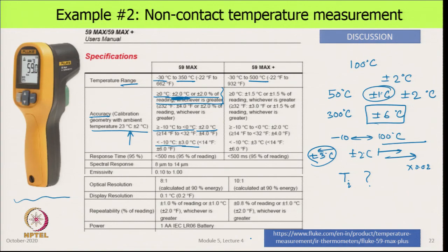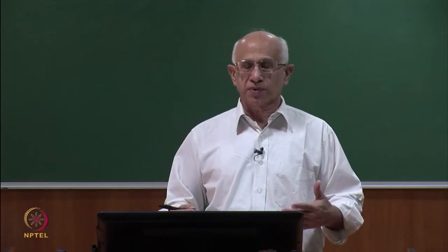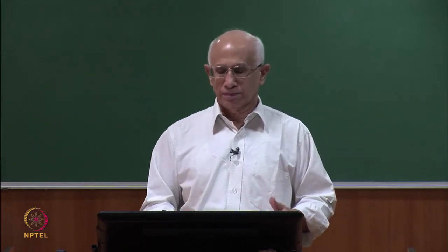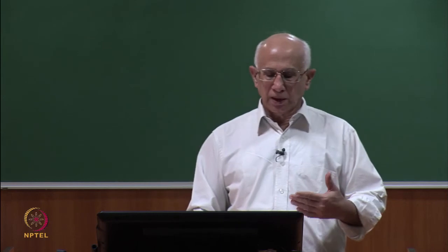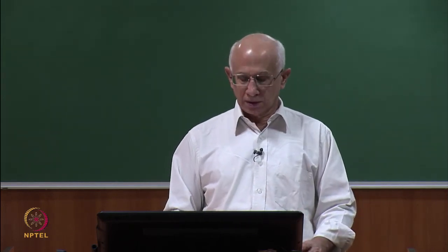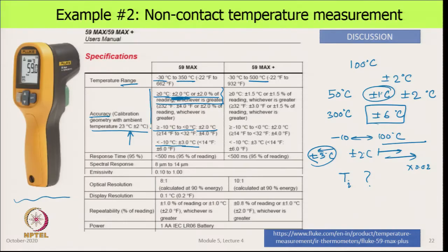So, it tells you that at higher temperatures your accuracy is less; your systematic standard uncertainty related to accuracy will go up. So, the same instrument can result in different values of systematic standard uncertainties. But this is the issue, that there are many instruments which will be quoted like this, and it is not just temperature sensors, but also pressure, force, torque, flow rate.